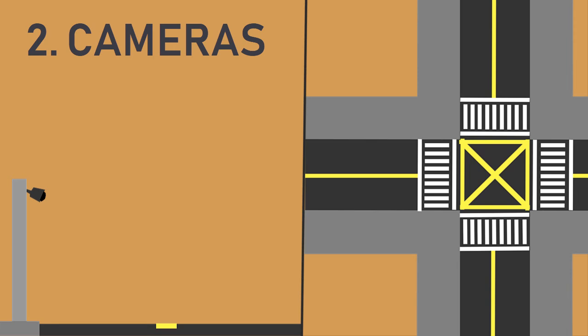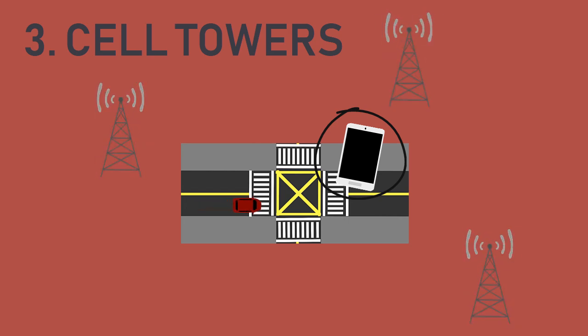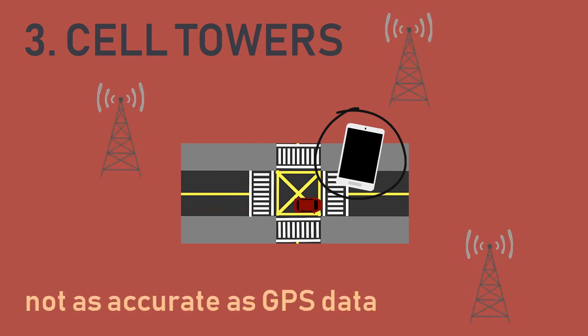Cameras, meanwhile, may be placed on the intersections of interest, and through the video produced, the vehicles that turn in the intersections may be identified through vehicle recognition software. Just knowing how many cars pass through one section of a road is insufficient, so you would also have to know where they're going. Cameras may be used to measure turns and match the amount of vehicles that pass through a road segment. The cell phone signals of a person inside vehicles passing through the roads may be determined through cell tower triangulation, although this is less accurate than GPS data.